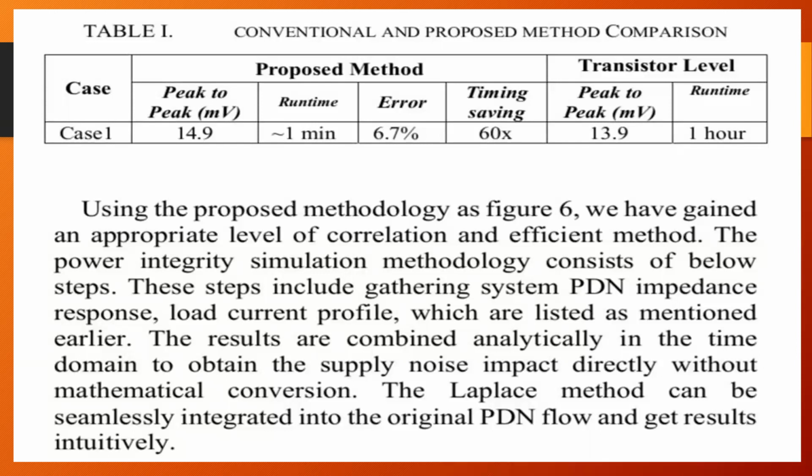Conventional and proposed method comparison. Using the proposed methodology as in figure 6, we have gained an appropriate level of correlation and an effective method. The power integrity simulation methodology consists of the below steps. These steps include gathering system PDN impedance response and load current profile, which are listed as mentioned earlier.